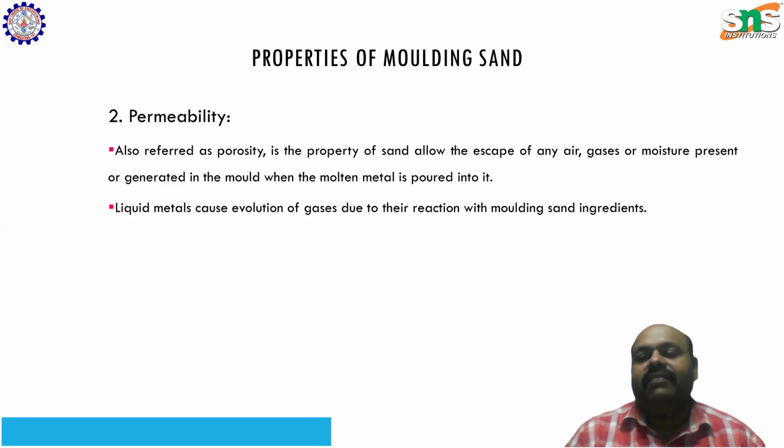Definitely there will be moisture in the molding sand, and due to the high temperature, when the liquid metal comes into contact with the molding sand, it evaporates the moisture, and that becomes gas, and it has to escape outside the total setup. Otherwise, it will create a lot of defects in the casting that we are going to get.